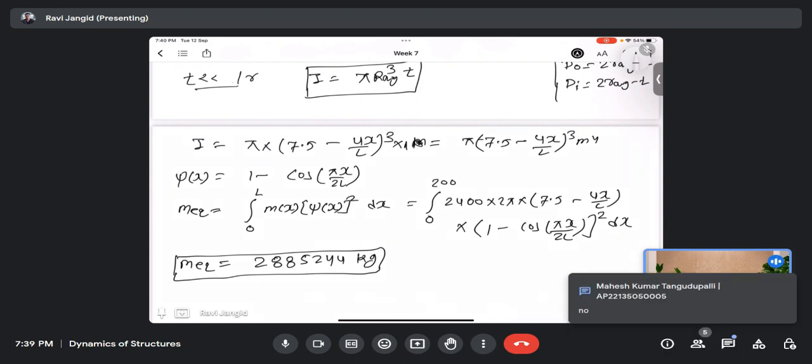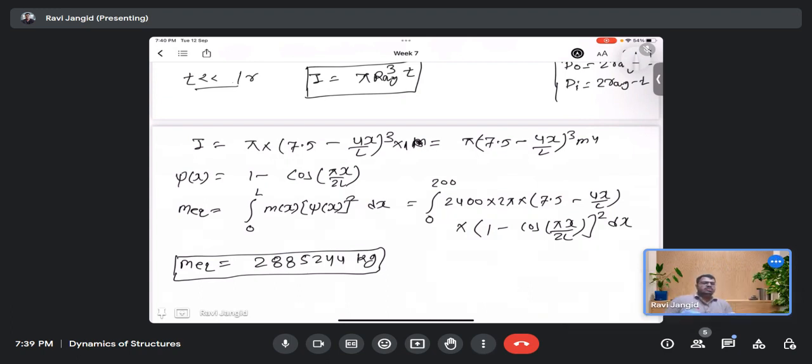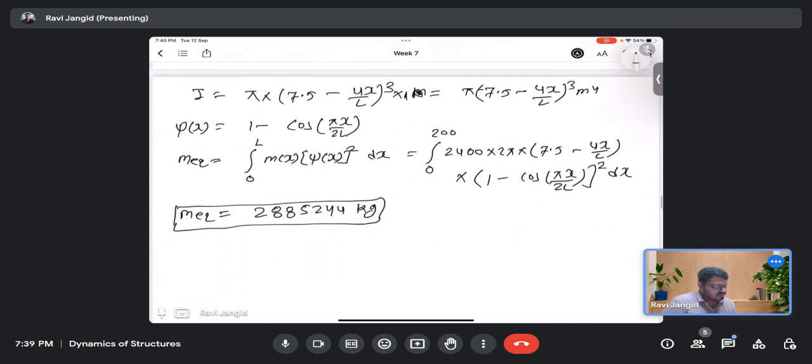After calculating the initial properties, it is simple like we have done. Now we need to find out the K equivalent. For this you need to do the integral from 0 to L of EI times psi double dash x square dx.